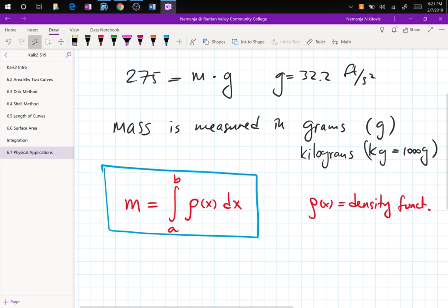So we can pick the data for the density here because that's what we measure in the lab. So I pick the density, and I snake the sine function through the points that I have in my data. And then I take that sine function and stick it in this integral, and I have 0 to 4 feet. These lengths are 4 feet. So I know it goes 0 to 4, and I will have to do my sine in terms of, again, imperial units, so feet and inches.